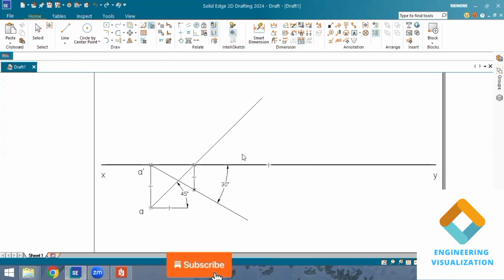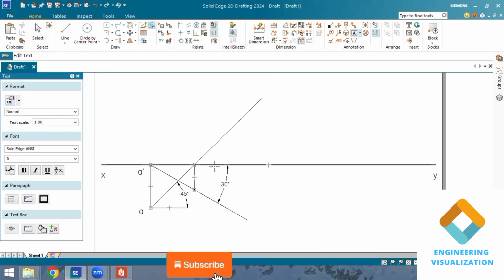Okay, now mention the views here. So here this point is exactly B, small b, and this is B dash. You can see the top views are connected by angle 45-degree and front views are connected by angle 30-degree.